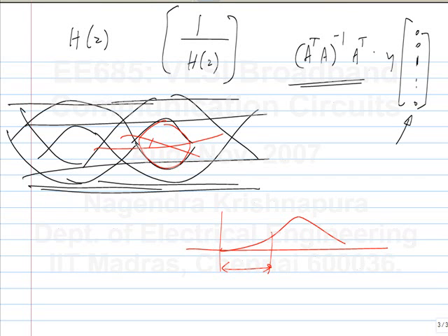So basically you are saying the eye opening is smaller, right? Yeah. What is the eye opening? I mean, how much is it? Okay, yeah, that's fine. It could be that it depends on the type of filter and the type of channel you use, right? There is no reason why the eye diagram has to be symmetric. It is symmetric in many cases, but not necessarily in all cases. If you have a first order RC filter, the eye diagram looks like this, definitely not symmetric in the x direction.